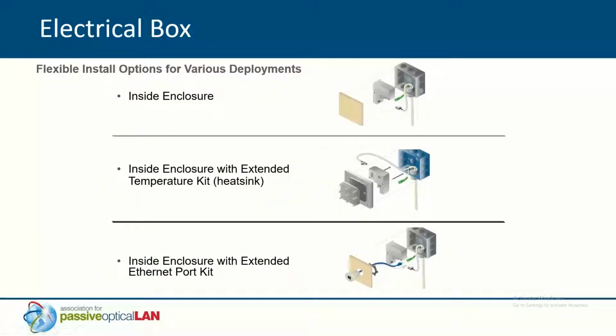Some of the very small form factor ONTs are allowing another option for design, which basically entails mounting the ONT in a small 4x4 electrical box or other enclosure. Let's say you've got a need for a camera or an AP out on a golf course or in a parking structure, somewhere where the distance is traditionally a limitation with copper.